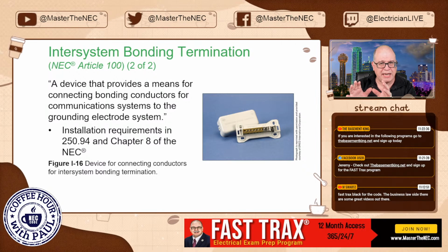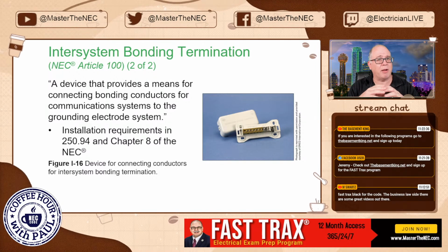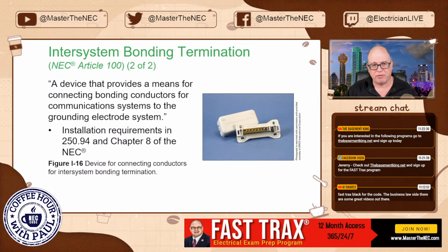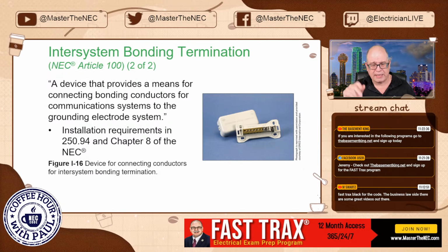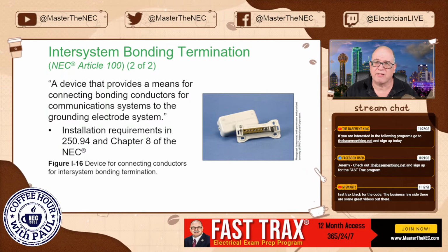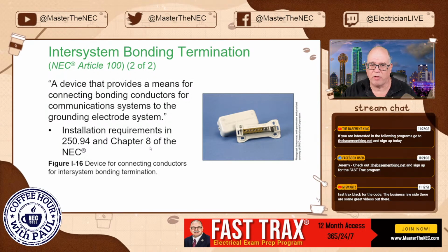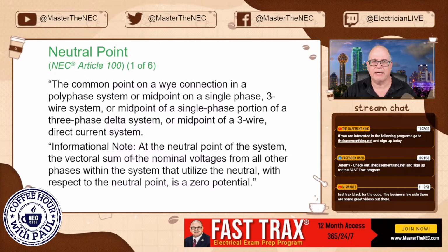This is just for communication, but they do allow you to install a bus bar under another option for intersystem bonding, which you could bring communication connections for their bonding, as well as things like bonding PV or CSST and all that. They do give you more options, okay?